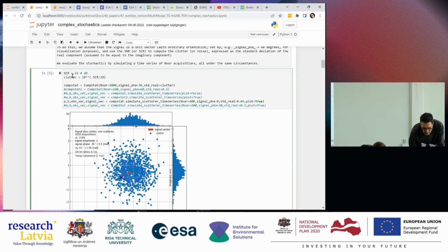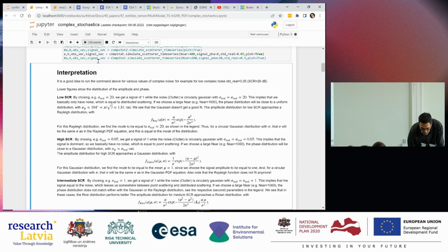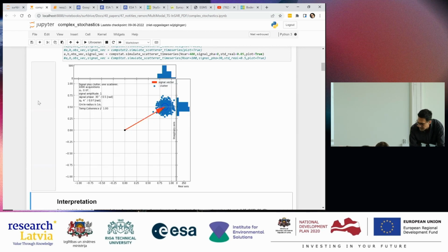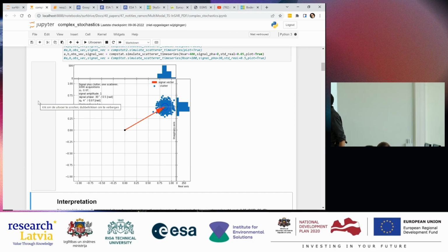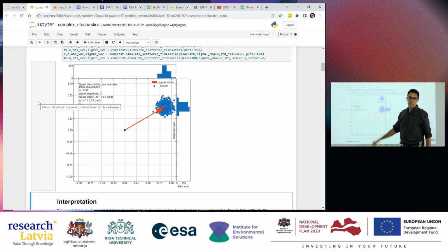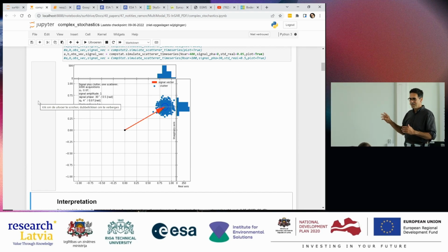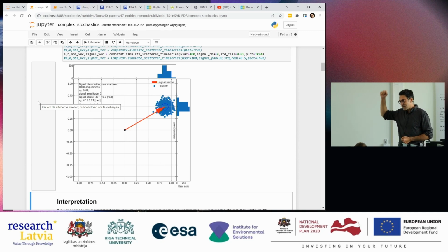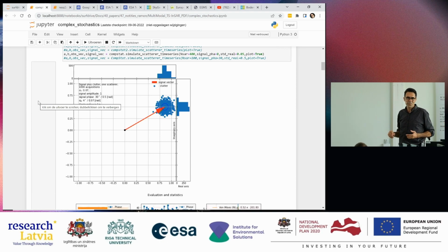So you can talk about the precision of the sensor, then we get up to about 23 dBs, I think. That is what we would enter here. If we have perfect data, I think for Sentinel it's 23 dBs. So what is the level that we can get then? That is this kind of situation. So the sigma of the phase is 4 degrees. And this is what gives us the sub-millimeter precision. So the sensor is able to do that. But every measurement that we get is the combination of the sensor and a particular area on the ground. And that is always different, and it changes over time. So it is impossible to answer the question, just give me the sigma.